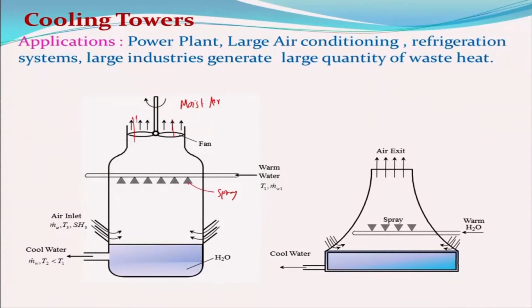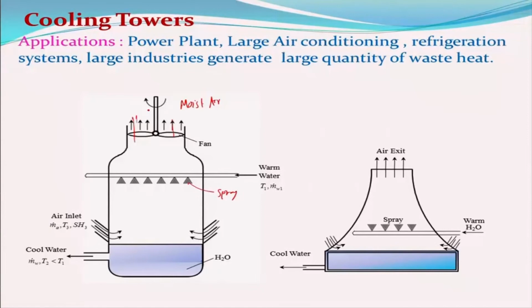As a result, a smaller amount of water will be collected here than whatever is going through. That water difference we call makeup water, because the difference is due to evaporation: some of the water is converted into vapor and carried away by the air through this sucking. For this you have to give some power, you have to use some energy.